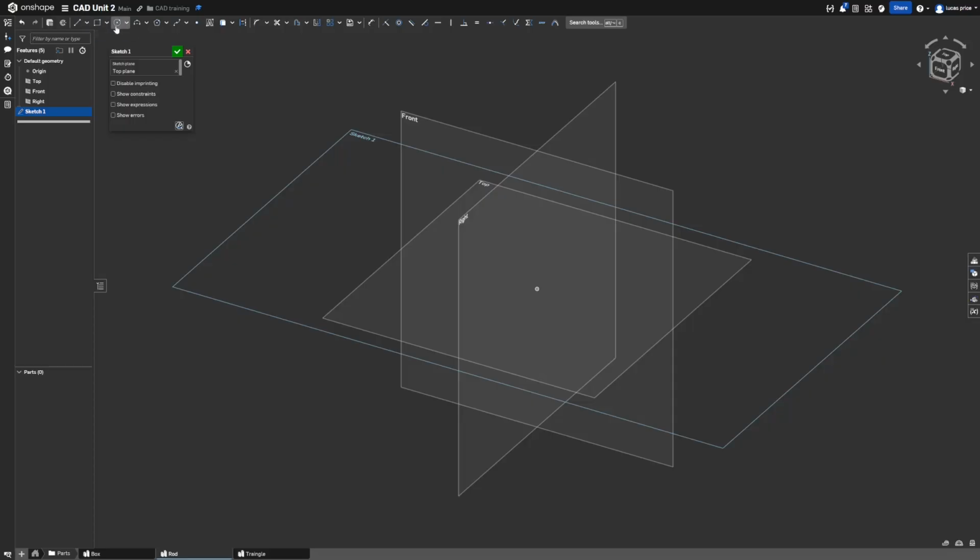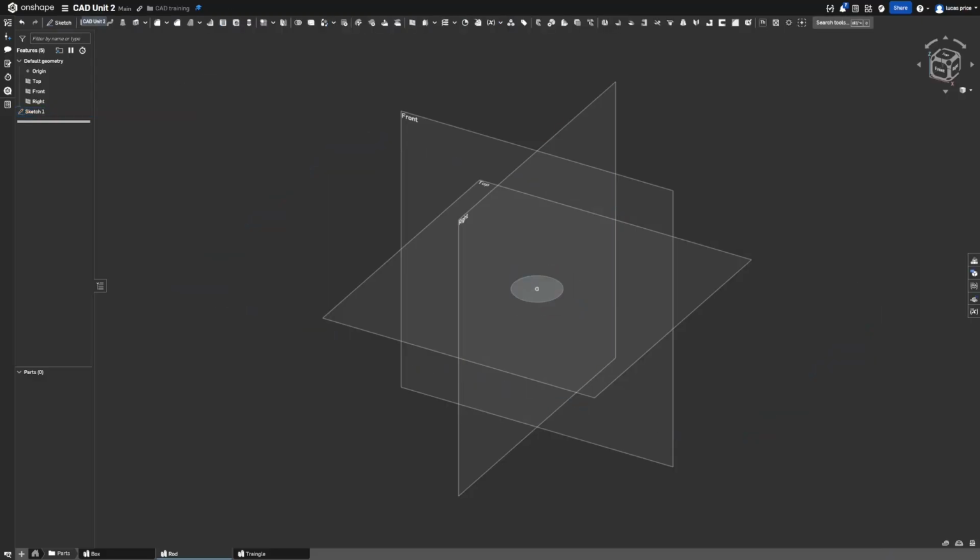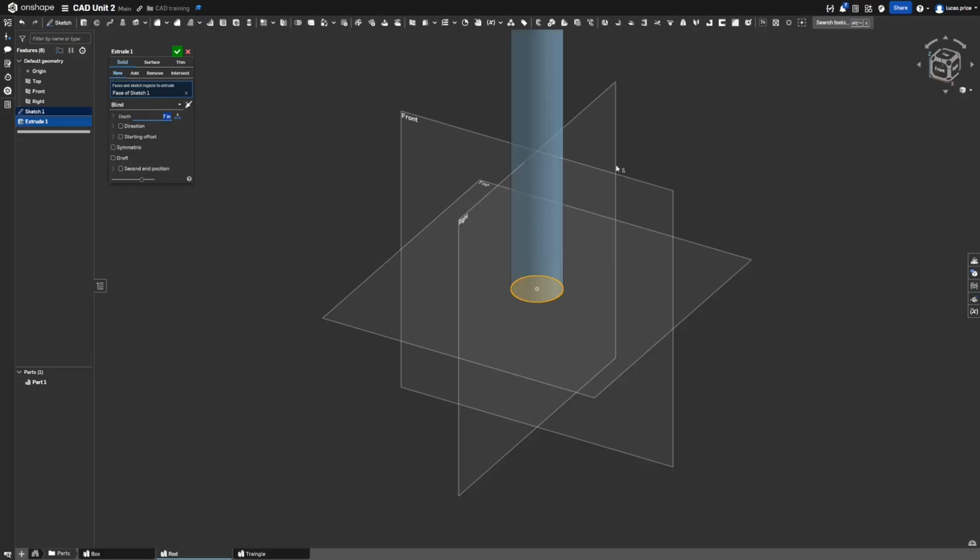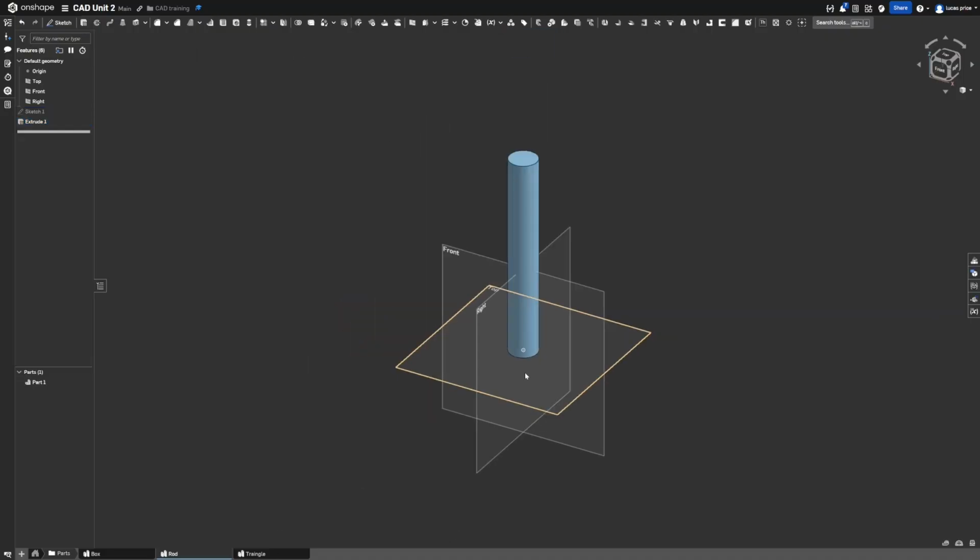Rod is pretty easy. Over there we made a 1-inch hole, so we will be making a 1-inch rod for this. Just dimension it out 1 inch. Extrude it. I'd say we made our hole around 5 inches deep. We want this sticking out a little bit, not too much. I'll go 7-inch rod. Should be pretty good.